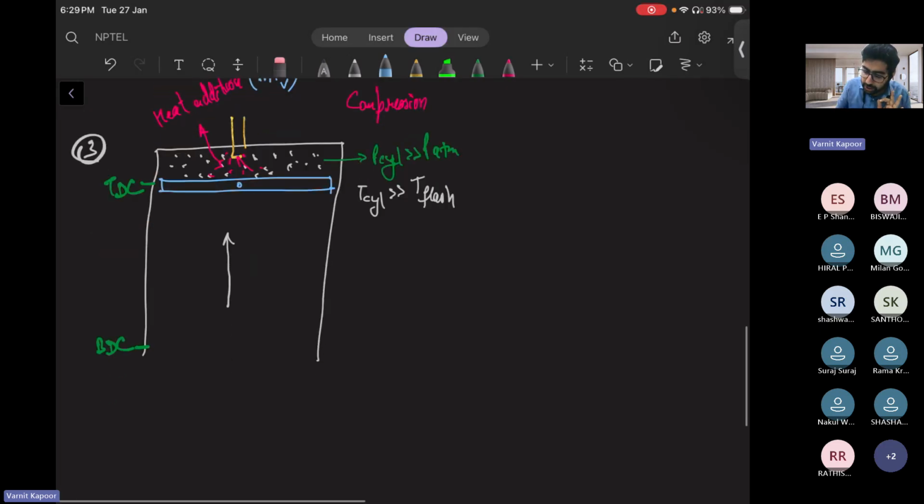So if you have seen the equation, dQ is equal to dU plus dW. From the laws of thermodynamics, your net heat interaction is nothing but the sum of internal energy change plus work done. If heat is added at constant volume, what is the work formula? General work done is nothing but PdV, pressure into change in volume.